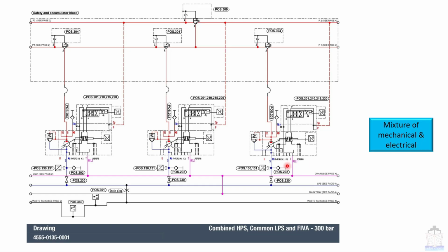Now once again I want you to focus on this point SP. In this configuration you can see that this SP is not connected with the B1 as we saw earlier, but this SP line is connected with this P2, that means the electrical driven HPS pumps outlet manifold. When a combined HPS system is installed on the ship, then this SP point is connected with the P2, not with the B1. Why? Because startup pumps start first, and on the basis of that pressure, the rest of the engine driven source plate pumps function. I hope this is clear.